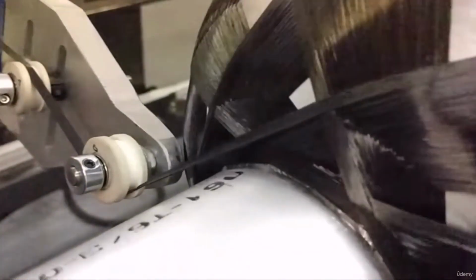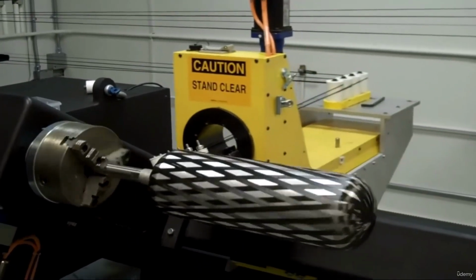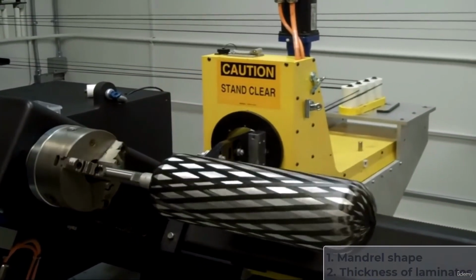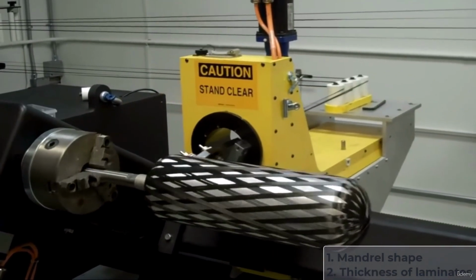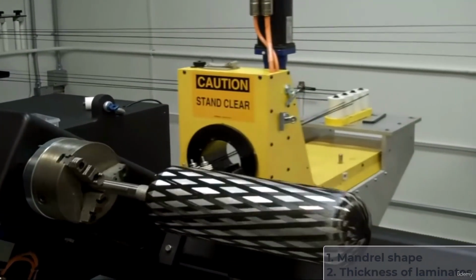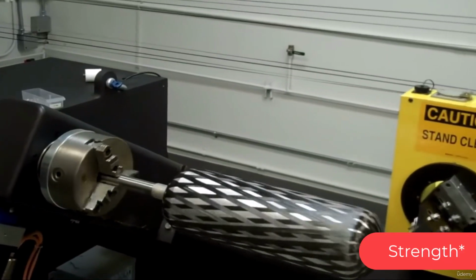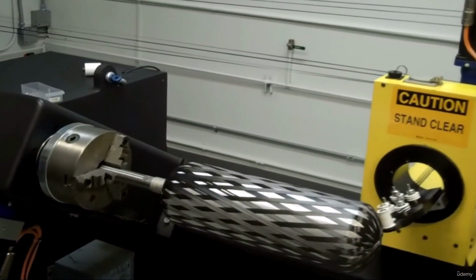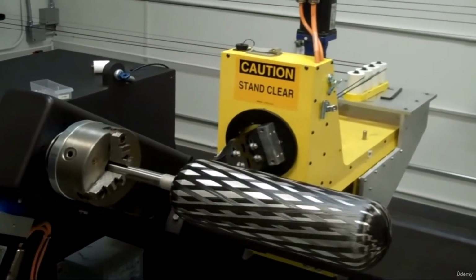When sufficient layers of tows have been applied, the resulting laminate is cured on the mandrel. The overall size and shape of the finished part are determined by the mandrel shape and thickness of the laminate. The winding angles will determine the mechanical properties of composite parts such as strength, stiffness, weight, and density of the laminate. The density of the laminate is the result of tension of the tows due to winding. Composite parts made through these methods generally have a good strength to weight ratio.